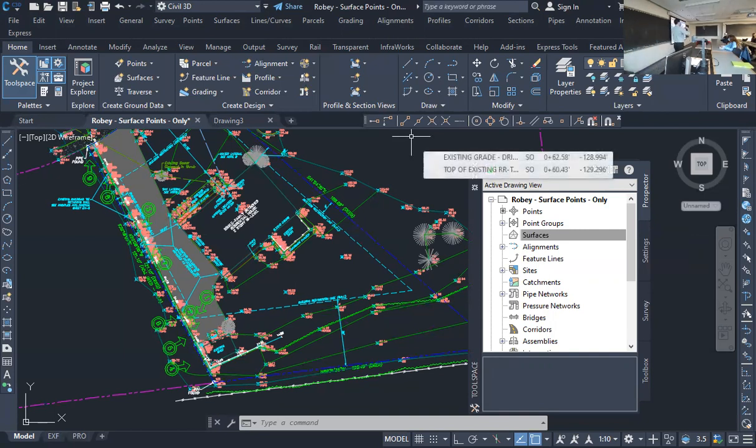if you started a drawing from scratch, if you tried to bring in the points and it gave you an error, it's because that particular point group style wasn't in. A lot of things in Civil 3D require their own styles. That base drawing that I gave you, if you insert that as a block, a lot of the styles are in there. I don't need to revisit that. Everybody kind of okay with that, inserting it as a block?